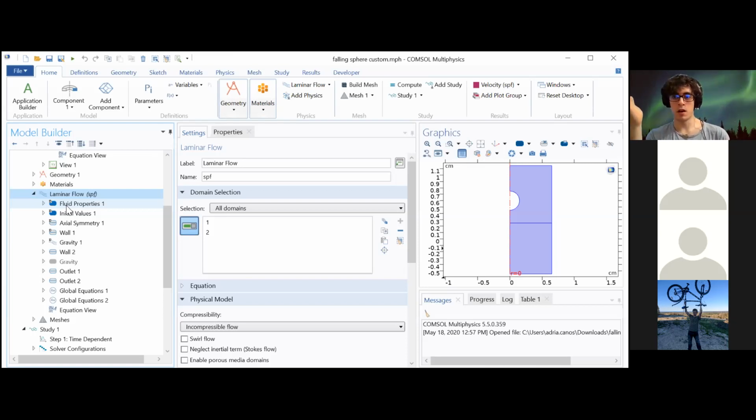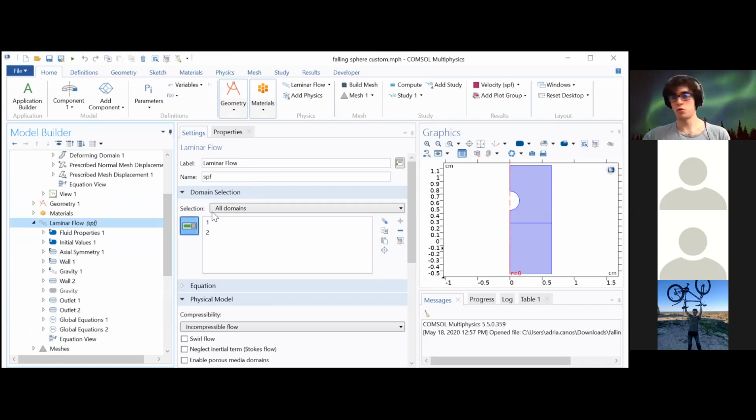Your temperature changes the thermal expansion coefficient, for example, and this you have to put inside the Navier-Stokes equations. In this case you have a direct coupling, and then you can choose different strategies. Usually, if your physics are not extremely complicated, it does not appear.